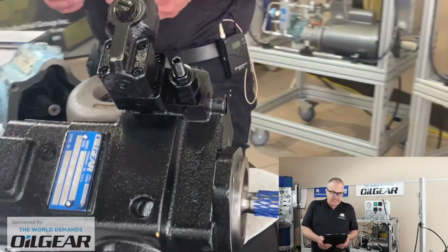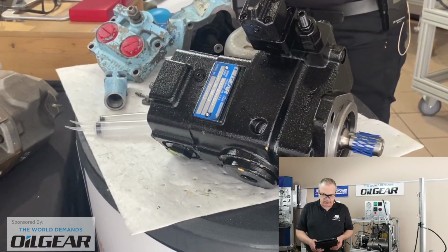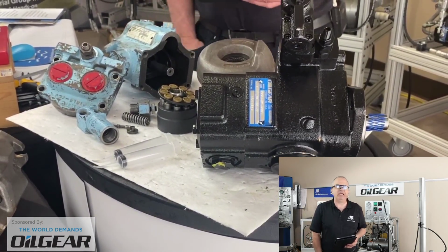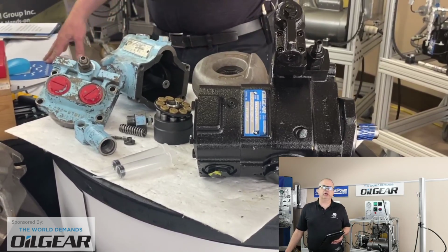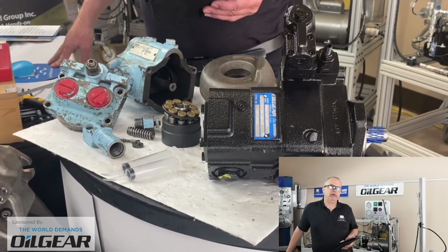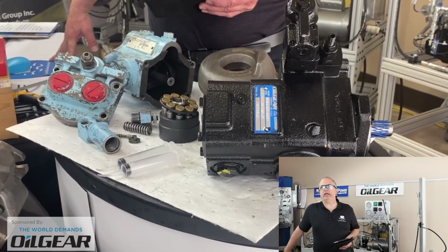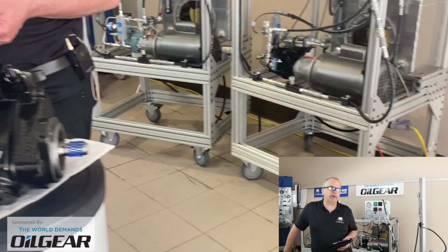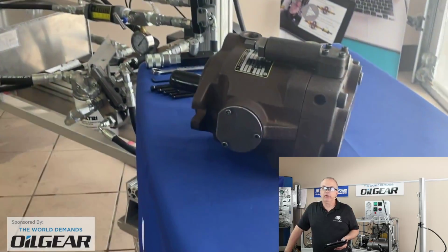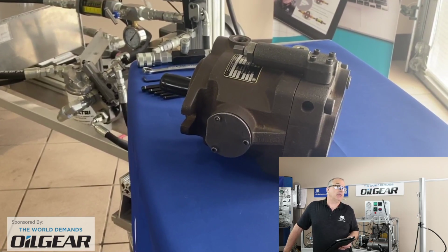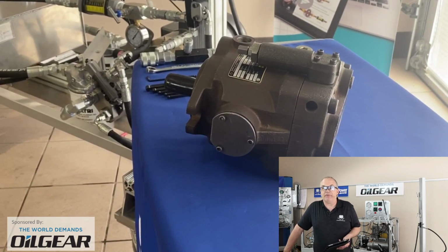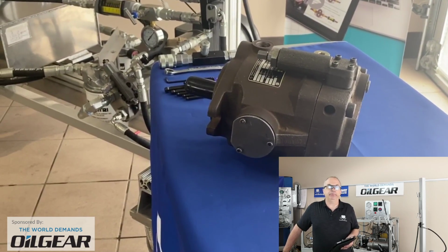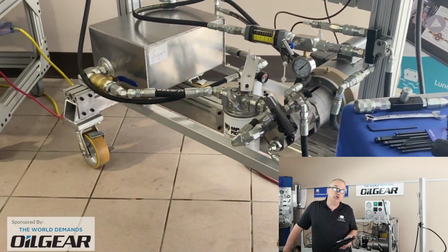Andrew asks, is case drain flow large enough that it could be a useful place to put the oil cooler? Yeah, you know, case drain flow is usually not something that you want to interrupt. Some pump manufacturers will say, don't let that pressure right at the pump's case drain outlet port get any higher than perhaps 1 bar, 15 psi. Other pump manufacturers will have a different scenario where they might allow it to come all the way up to perhaps 75, 80 psi, perhaps 5 bar, but usually no.